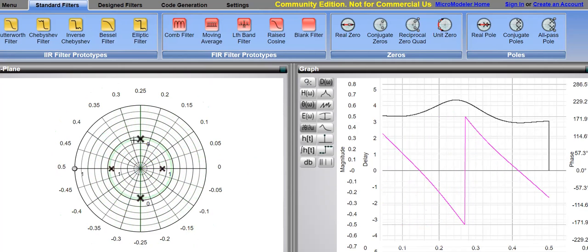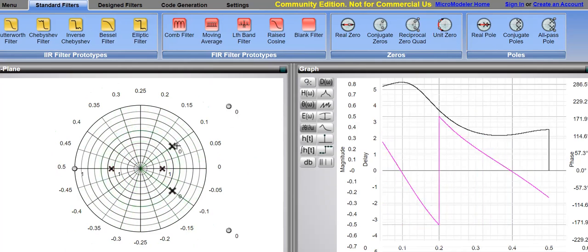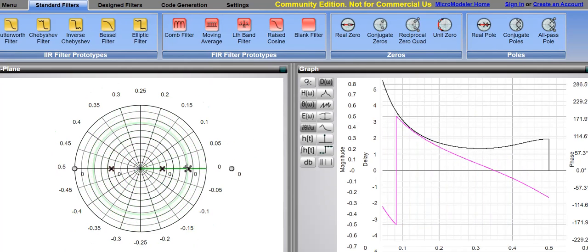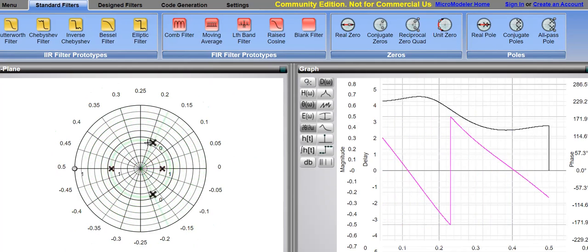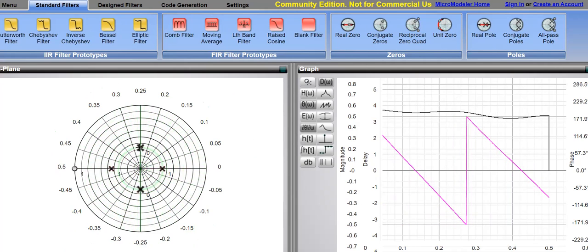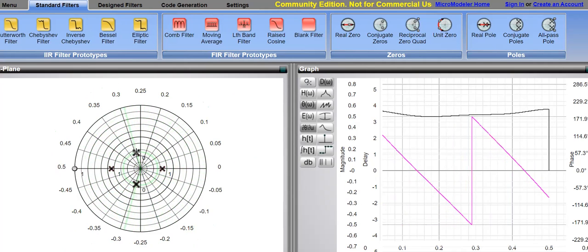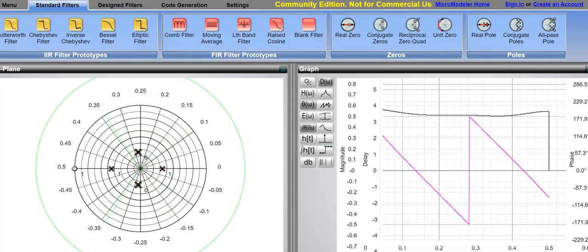So this is the full story. Here we have two filters. One is the all pass filter, and the other is our conventional IIR filter, which helps us do our particular job. First, the IIR filter gives us the strength to filter it out, and the second, the all pass filter, gives us the advantage of a constant group delay. Otherwise, there is some distortion, which is known as phase distortion.